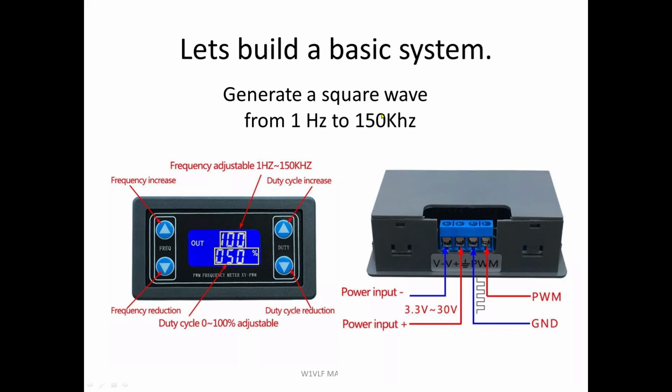Fred and the guys like to use 600 hertz because they're listening by ear. That has advantages of a very simplistic receive system without the use of a computer. But if you go up to 16 or 18 or 20 or 30 kilohertz, then you can use an SDR with filtering, with all sorts of different detection modes and so on.